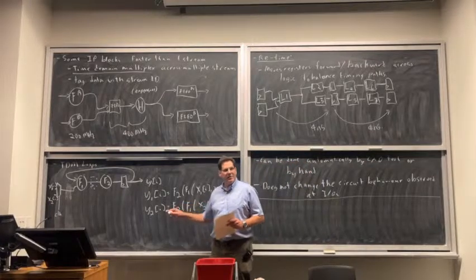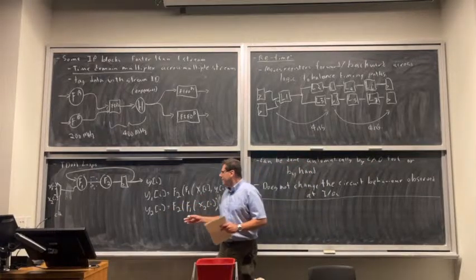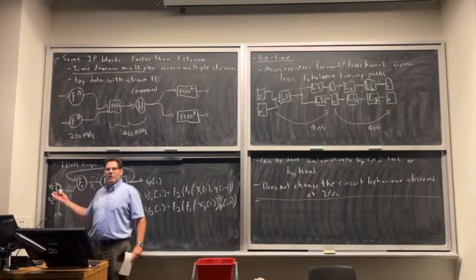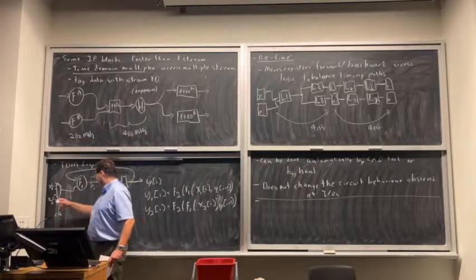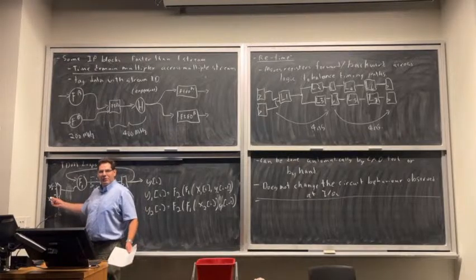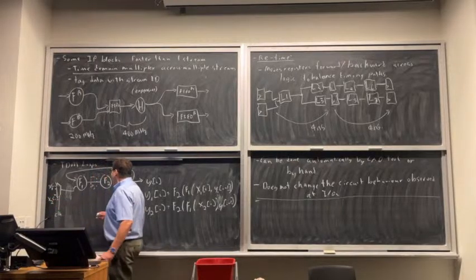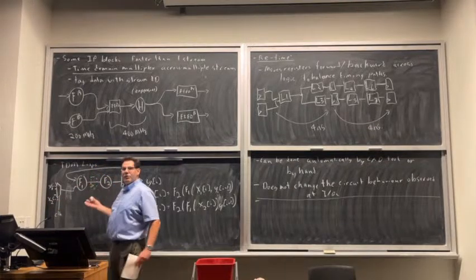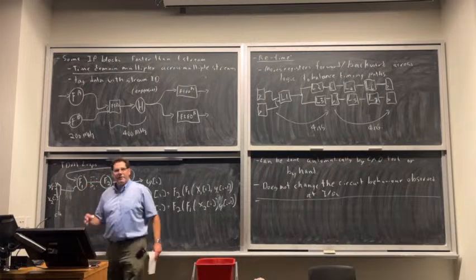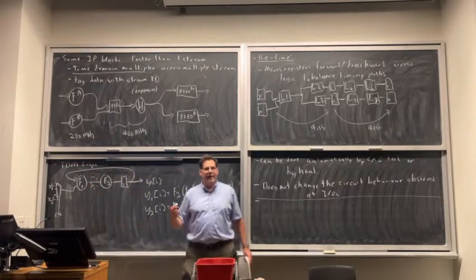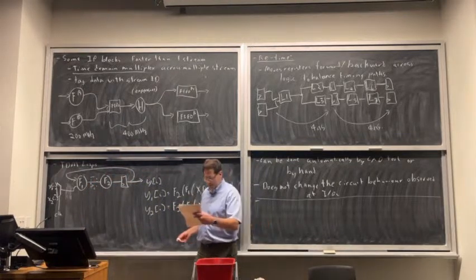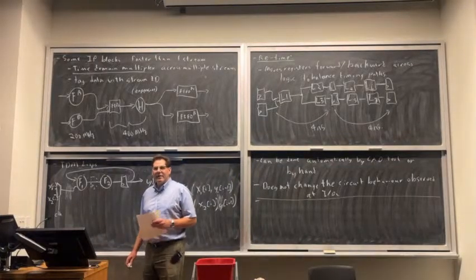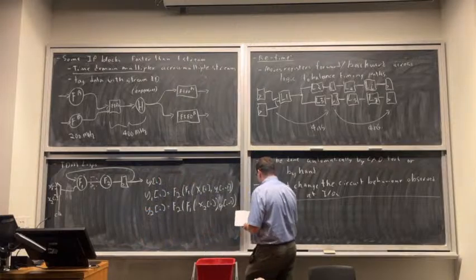Okay, so does that make sense? It only helps you if you have more than one stream of data. If you only had one stream of data, this doesn't really do anything useful for you, because the second stream would just be putting in a bunch of zeros. So that's kind of useless. But if I did have two streams of data, it means I could actually use one copy of this unit, pipeline it, clock it faster, and maintain approximately the same throughput. Does that make sense?